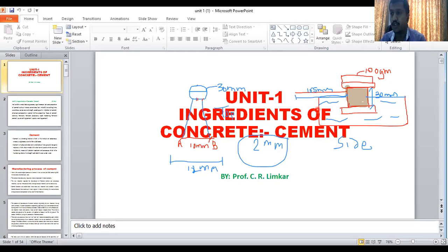But before filling, make sure you have attached the glass plate at the bottom. You have filled the cement paste. Then you have again placed the glass plate at the top side. You have placed one weight on that particular glass plate. And this prepared mold, you are going to keep it in the water sample. The room temperature you have to maintain is normal room temperature, around 27 degrees centigrade. You have to keep this mold in water for 24 hours. How much? For 24 hours.